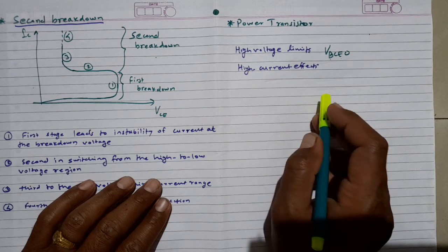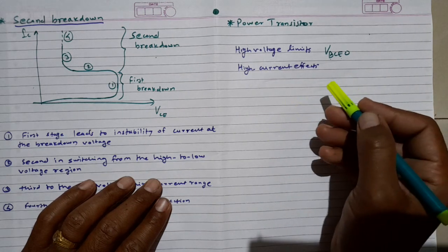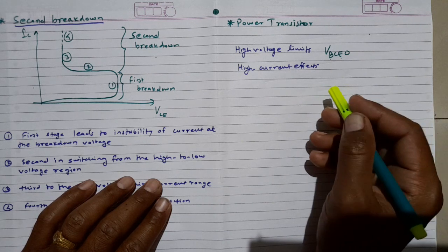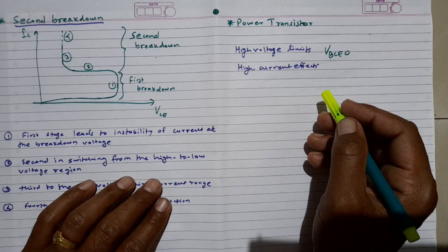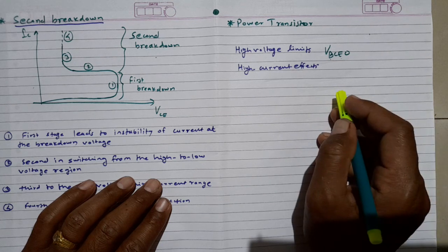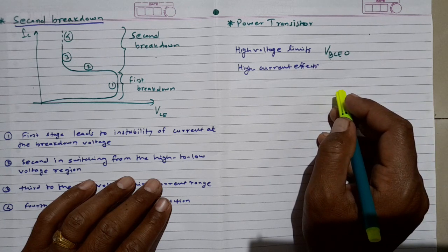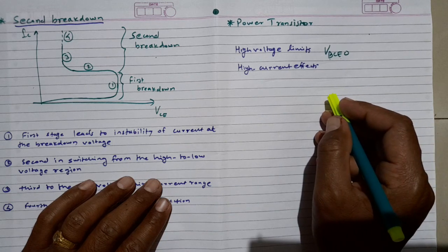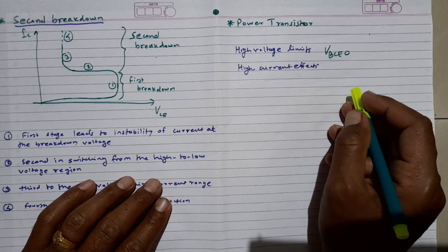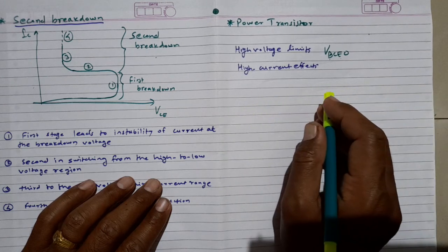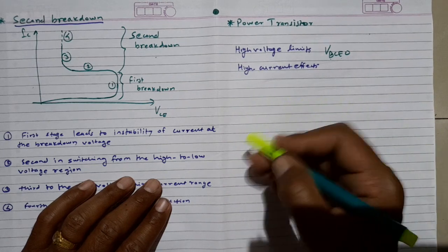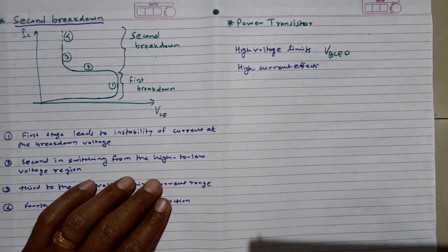Also, in order to obtain a very high breakdown voltage, the collector doping must be reduced. The low collector doping not only exacerbates the Kirk effect, it also induces a region of quasi-saturation due to the conductivity modulation in the collector.